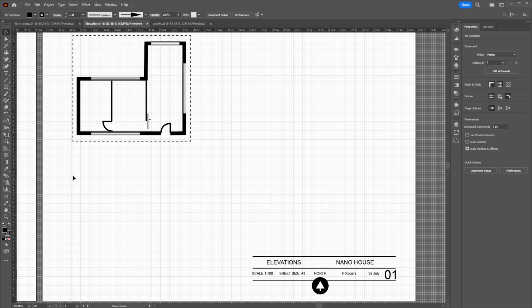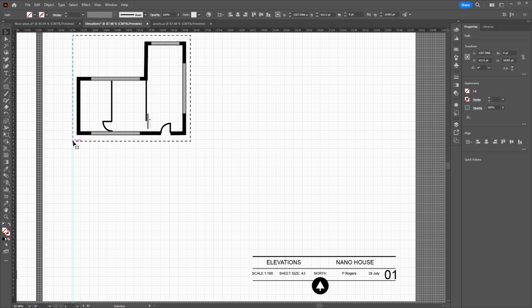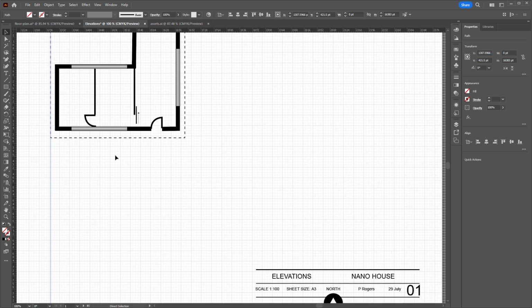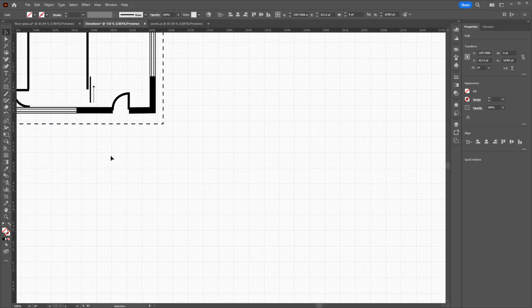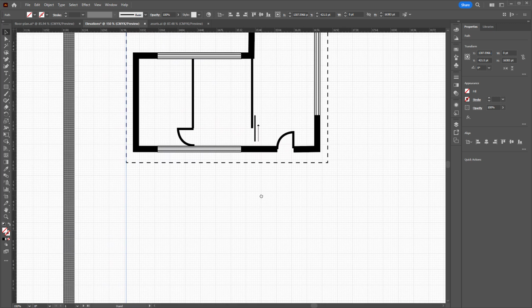So if I drag out a guide on the furthest edge, which is this roof that extends beyond this wall here, I can place one there. And I'll hit Control Plus on the keyboard just to zoom in a bit, and space bar and click and drag. And I'll grab another guideline and click and drag, this time at the edge of the building or house on the left side, and I'll do the same to the other side as well.